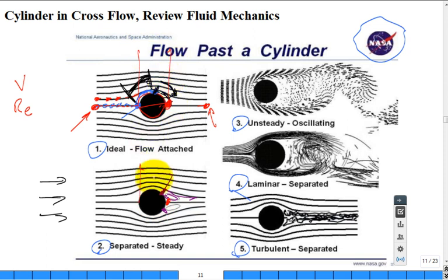In this case, there's not a complete pressure recovery. It's a lower pressure on the back side because of that separation. Why do we have separation? It's not a favorable pressure gradient. The fluid doesn't want to do that. I mean, it's slowing down and moving into a region of high pressure. It wants to not do that. It'll skirt out the sides, slip out.